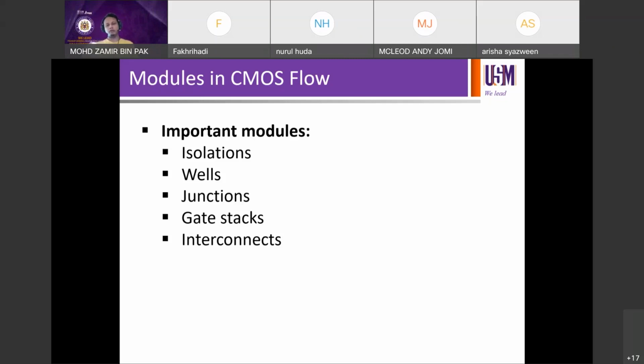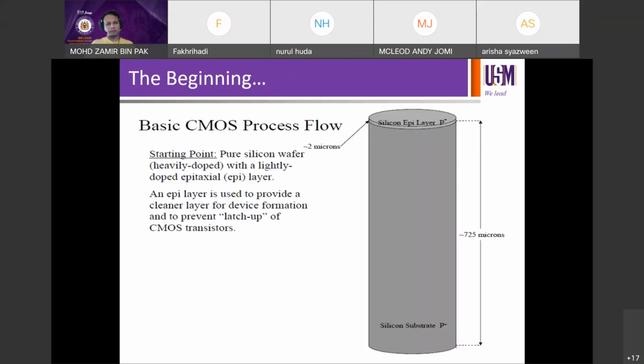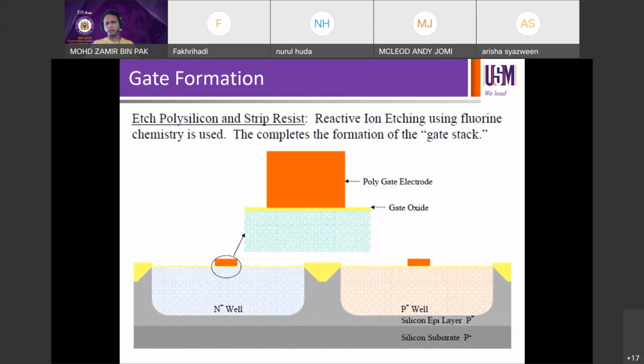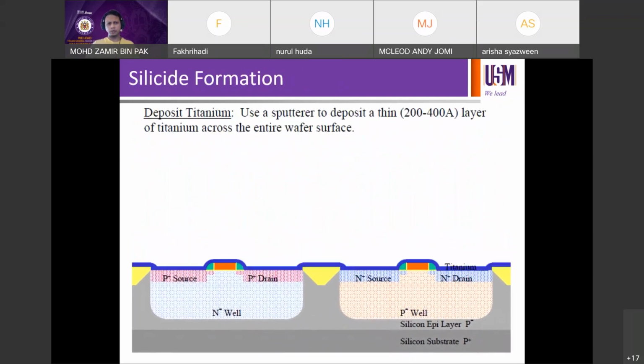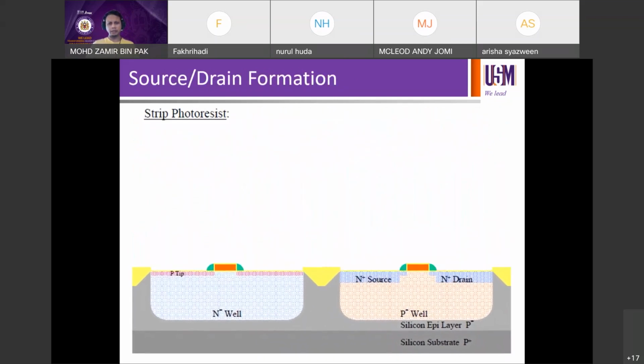So the moment you have finished those, the wafer is ready as a piece. Eight-inch, 12-inch, 18-inch, whatever your fab is running. In our case, 8-inch, for example. Then you finish up to that level, and then you're going to run your test. Test is another thing. We call that e-test, electrical test. So e-test is normally done. We call that electrical test.